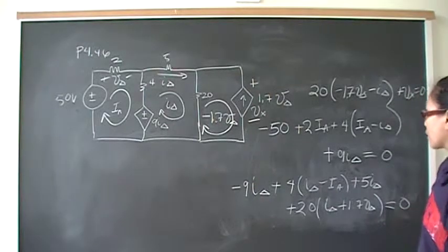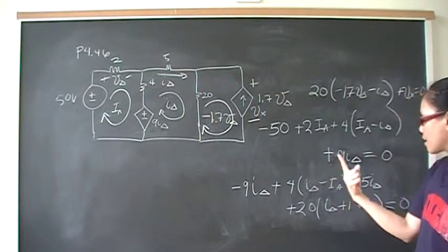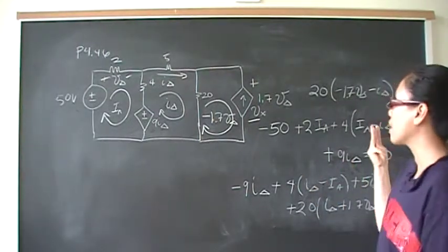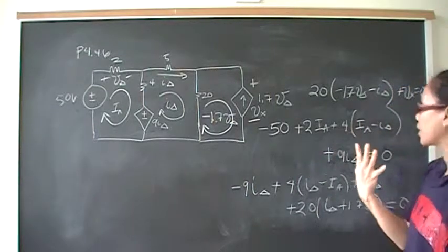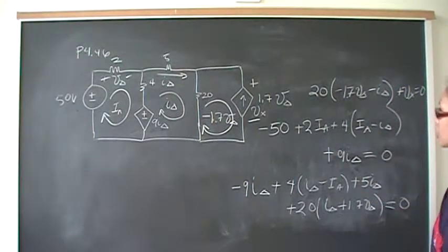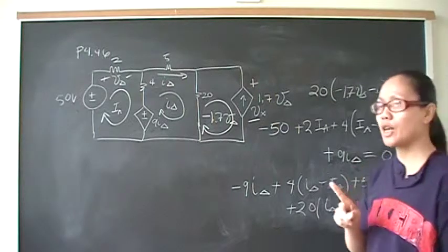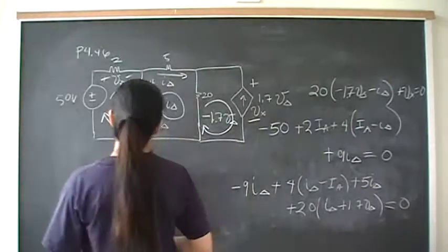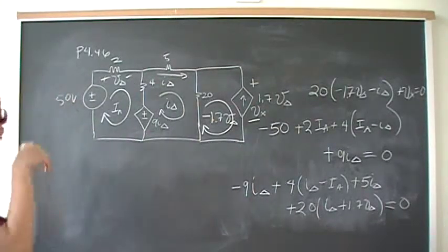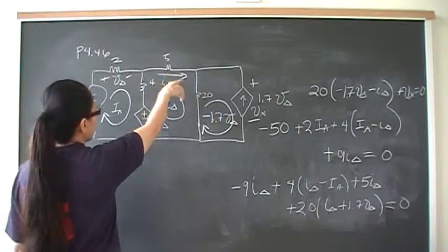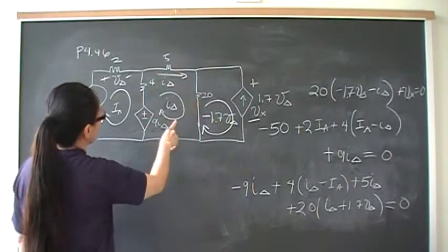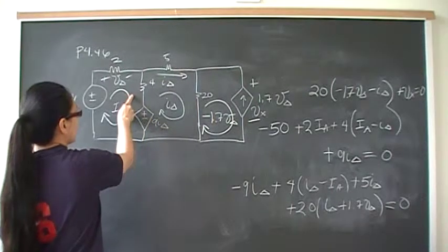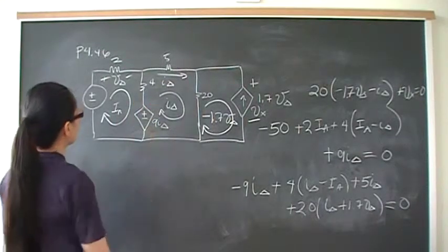Okay? So now my unknowns are I delta, IA, V delta, and Vx. We have 3 equations from our 3 meshes but 4 unknowns. That means we have a constraint equation that's going to provide our 4th equation. So we have 2 options for constraint equations. We can say I delta is equal to IA, the sum of this and this.